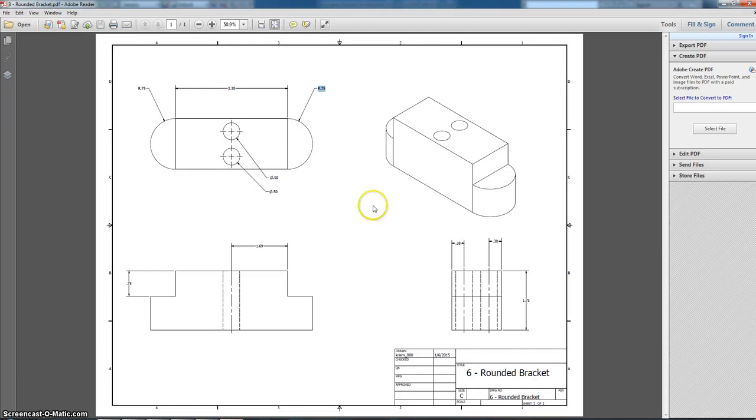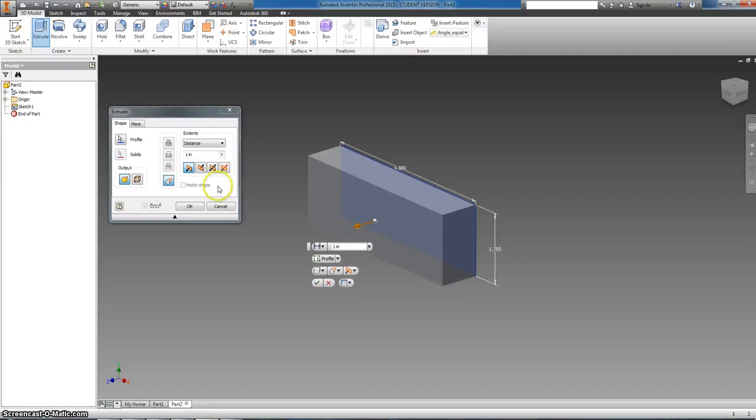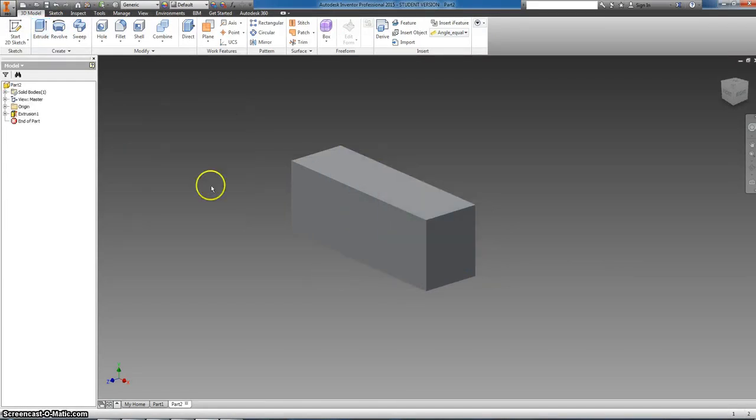And going back to the drawing, again, the depth and how much we have to extrude isn't necessarily given to you, but we can determine it by looking again at the radius. We know that from here to the center point is going to be 0.75, and the same goes for this distance. So if we add those two together, our full depth is going to be 1.5. So going back to Inventor, we'll hit 1.5. And there is our outermost block of clay.